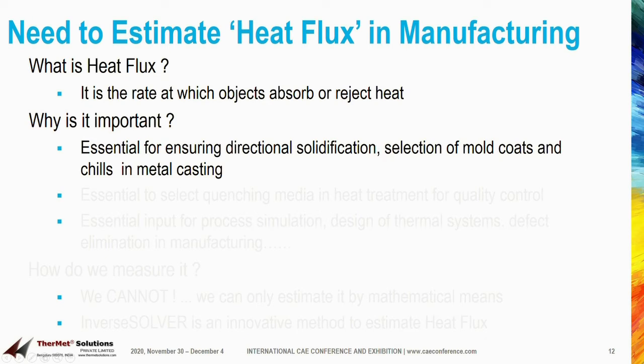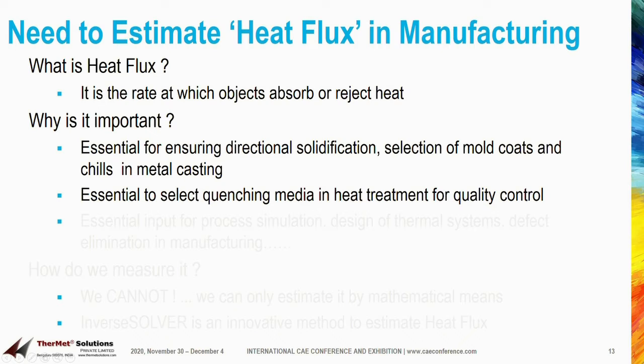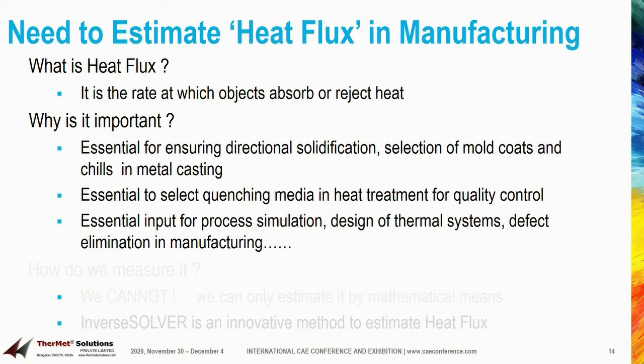Take metal casting. An estimate of heat flux is essential for ensuring directional solidification. Selection of mold coats, chills in metal casting, etc. are governed by the heat transferred from the liquid metal to the mold. In heat treatment, the selection of proper quench media affects the final properties of the components. It is an essential input for process simulation, design of thermal systems, elimination of defects in manufacturing, etc.